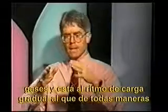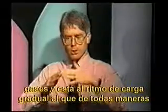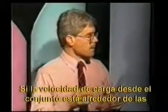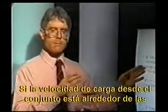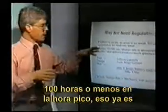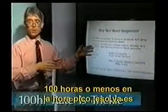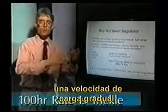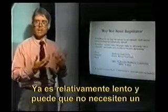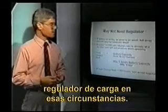It's effectively at the trickle charge rate that a charge regulator would take you to anyway. If the charge rate from your array at the peak of the day is around the 100-hour rate or slower, that's already at a trickle charging rate. You're already relatively slow. You may not need a charge regulator under those circumstances.